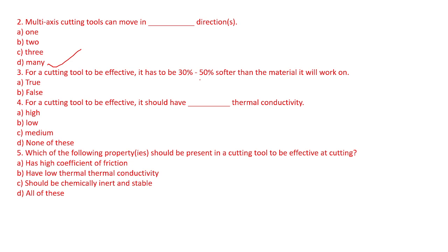Okay, and it has to have high thermal conductivity. See, approximately 70 to 80% of the heat goes by the chip, 20 to 25% goes by the tool, and 5 to 10% goes by the workpiece. So you can see that the tool takes a significant heat portion, so it has to have high thermal conductivity, right?